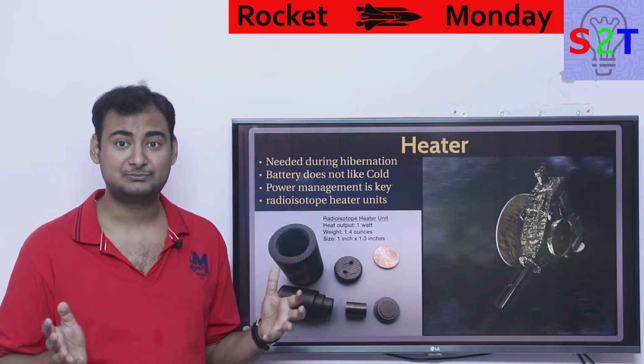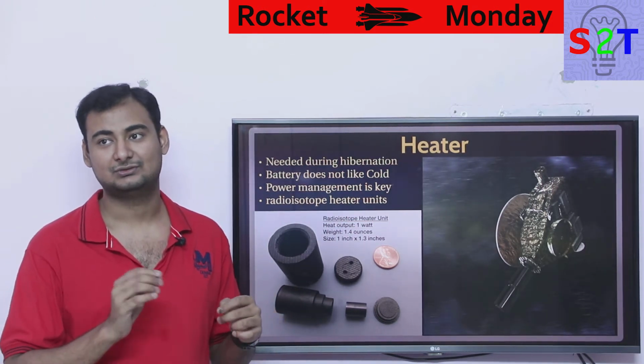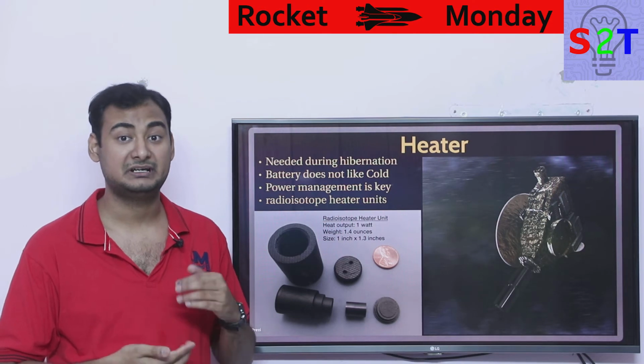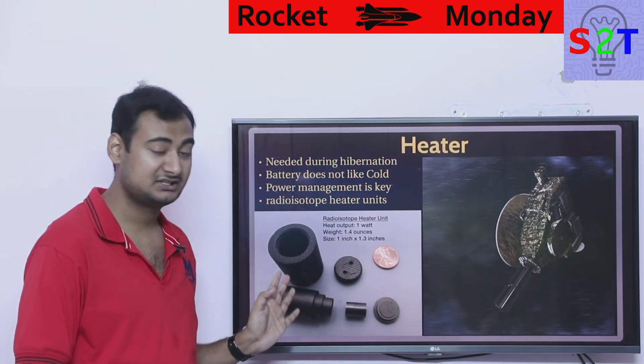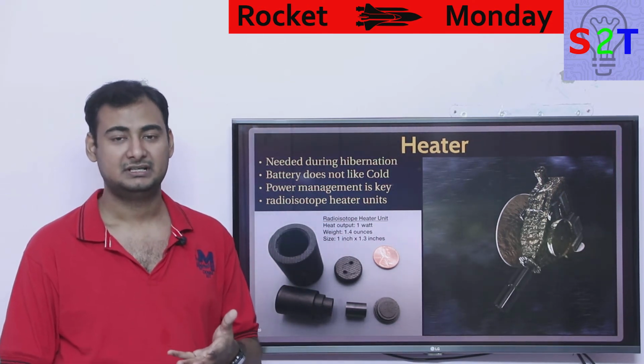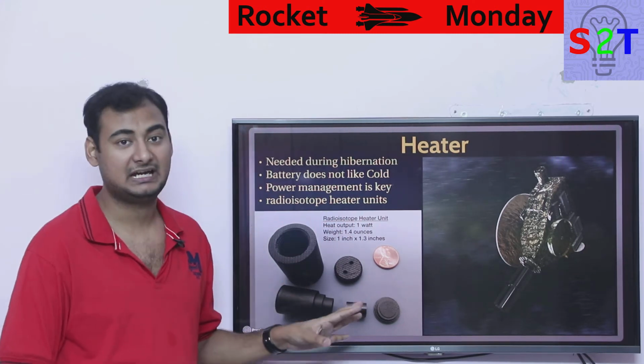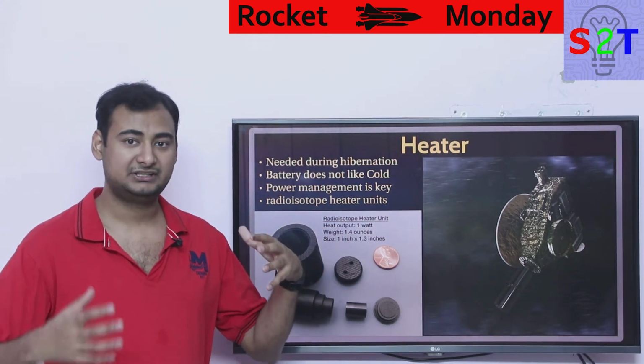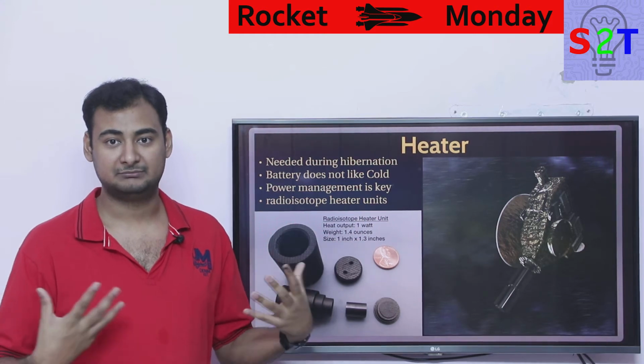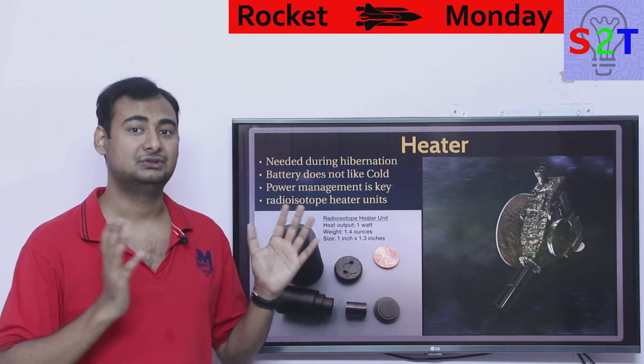Now, in the case of the Cassini probe, 100 plus were used to make sure the critical components always remained above a certain temperature, and these also act as a very good temperature reference. So that is why we have to figure out heaters. Generally, when you are talking about a human or anything big and bulky like a space station, you have to worry about cooling.